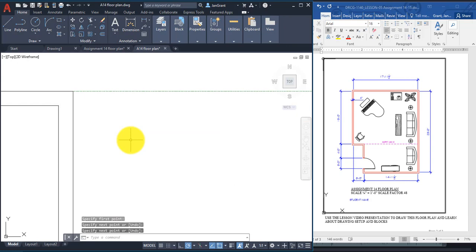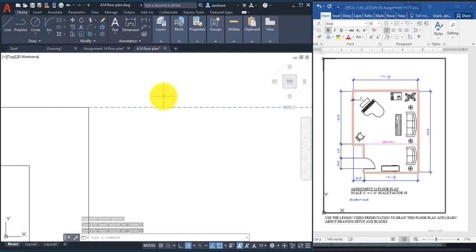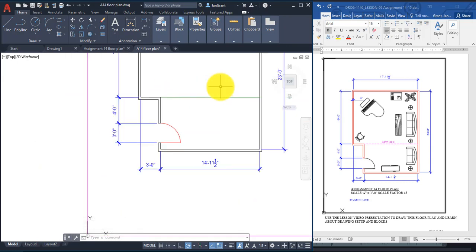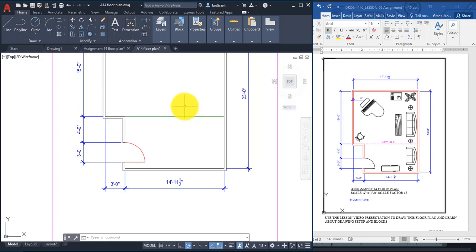And you can see here that there is a really small hidden line, but the scale factor isn't appropriate and it won't print. It'll print solid. So we type in LT scale and we just try the LT scale that would be suggested on the chart. If we type in 48 and enter, what's also unique about AutoCAD is that you can type in whatever number you'd like.